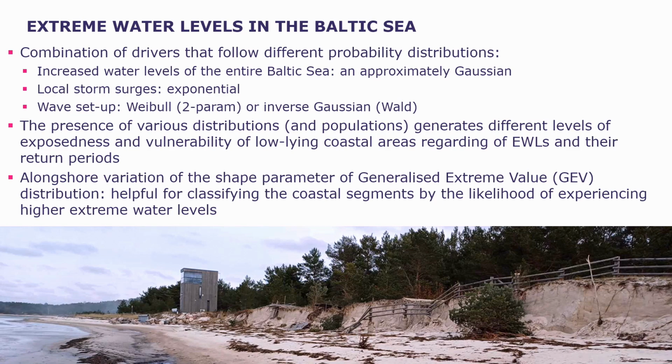The local water level in the Baltic Sea is a combination of joint impact of several drivers that follow different probability distributions, and the presence of various distributions generates different levels of exposedness and vulnerability for low-lying coastal areas regarding extreme water levels and their return periods.